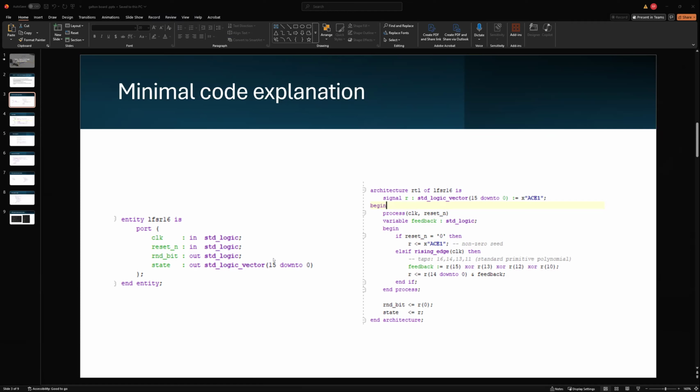In a process block, what usually happens when we code it in VHDL is the process block is based on a clock and a reset signal. So what the reset does is when the reset is zero, the data basically goes to default. And the other stuff is based either on the rising edge, which is the part where the clock first reaches one, or the falling edge, which is the other way, when the clock first reaches zero, or when it is falling.